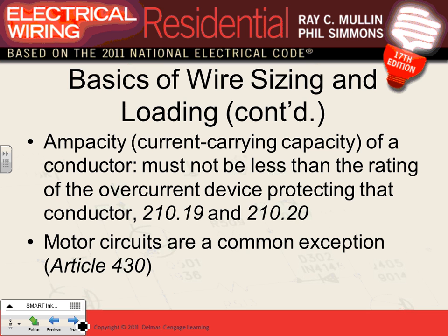Let me draw a very simple circuit here. I have a 20 amp circuit, and this is a branch circuit going to a machine to feed it. My conductor, based on the NEC code book, has to be number 12, as we know, right? Number 12. Anybody can tell me what the code calls this branch circuit? This is a 20 amp branch circuit. The rating of the branch circuit is the rating of the overcurrent protection device ahead of it. So this is a 20 amp circuit because of the 20 amp overcurrent protection device.